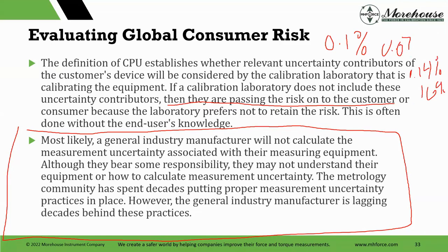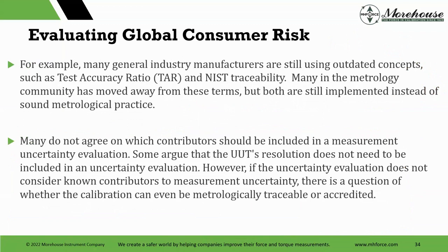What did you do?" Manufacturers sometimes are going to say, "Hey, we just took the average." Well, the average hides extremes. Or they're going to say, "Hey, that spec was developed under ideal conditions, which you are not operating at." That is what we hear a lot of. Yes, you are derating the device. They weren't conservative in their specification. They used marketing speak or gospel to sell you a product that now you're thinking you have something that's good to 0.1%. In actuality, probably like 0.15, something like that, just to be aware of it.